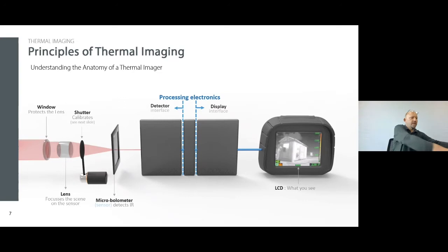And actually, if I show you that on the front of this camera, this is the germanium window here, and this is actually a user serviceable part. So you can pull this window off and change it, because this is the bit you point at the fire, and this is the bit that tends to get damaged if you lay it down in a fire situation.